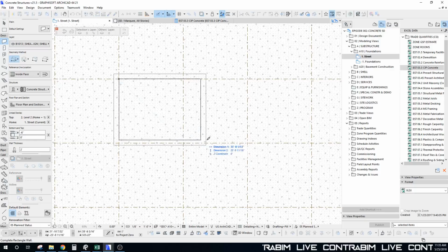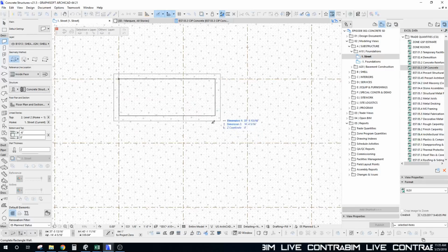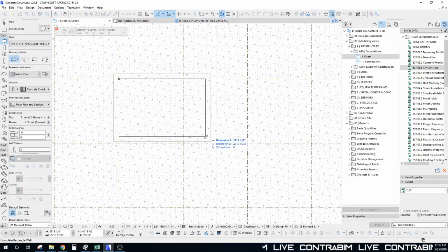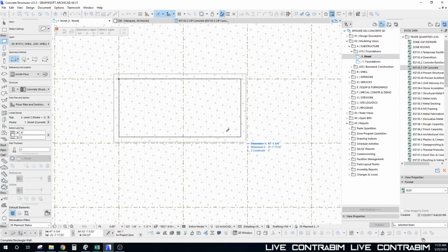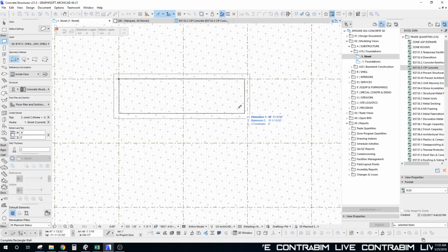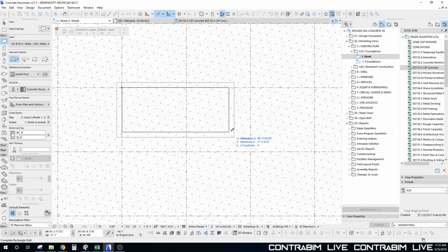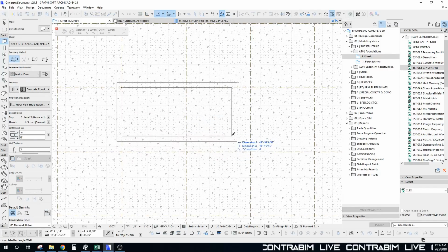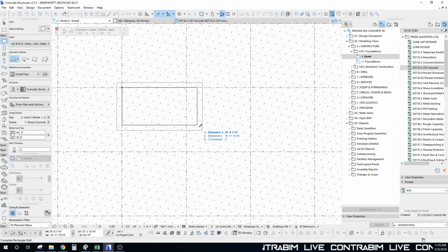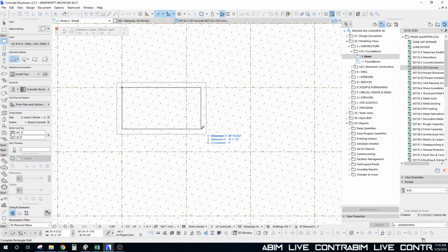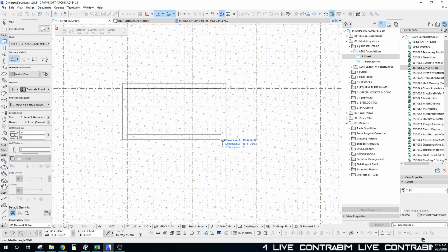So in terms of the size of the core, this is obviously dependent on how many elevators and stairwells and additional rooms and functionality you might need, depending on what your building type is, for a high-rise concrete structure. In this case, we're essentially modeling something based off either a hotel or a high-rise residential apartment or condo building. So one of the main things you want to think about is that inside clear dimension. And having the reference line for this tool on the inside actually makes it a little easier to determine that specific inside clear dimension.